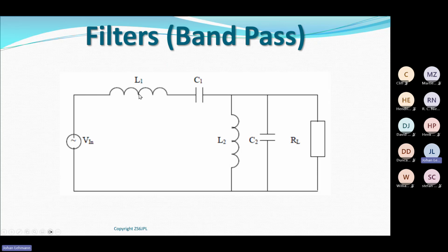And these two obviously are only on honeymoon and in harmony when they are at resonance. So at resonance, the impedance of the series tuned circuit is very low, so the frequency flies past. This one is resonating at that same frequency, so it's a very high impedance. It doesn't affect my circuit, and it goes past to the next stage of my radio. So you can work it out for yourself easily if they give this drawing for you in the exam paper.